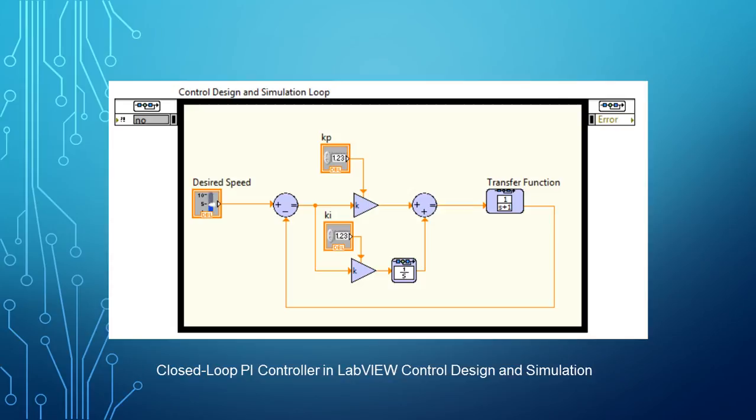Next, we are seeing the control design. This is the control design simulation loop. When designing a controller, it is best to fully understand the plant, in our case, the DC motor. This understanding comes from analysis of specialized graphs such as Bode, root locus, and Nyquist plots, which build intuition of how the plant will behave. Graphs in the time domain, such as the step response, provide immediate feedback on the ideal behavior of the system, such as rise time, overshoot, settling time, and steady state error.